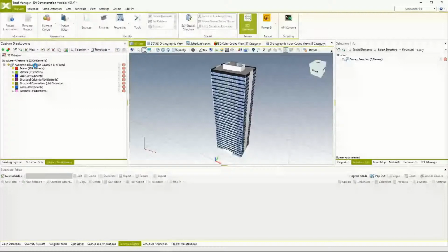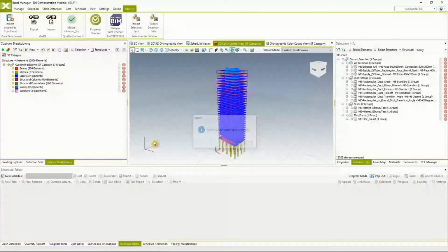So we're going to use rooms by area selection sets. Let's check if it's imported. We're going to use a flow rate selection set template as well. And then we're going to try to create the same CBS templates. So first let's make rooms by area.